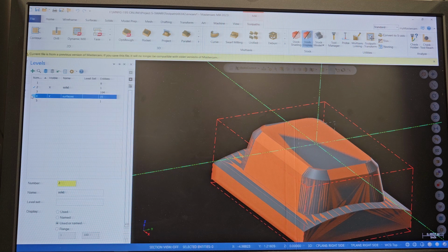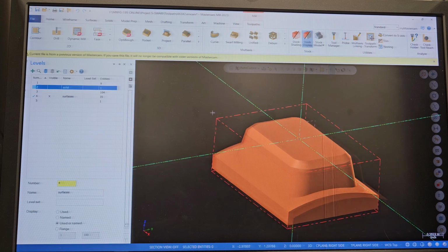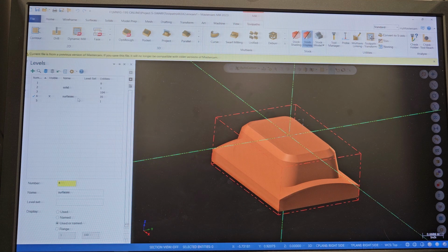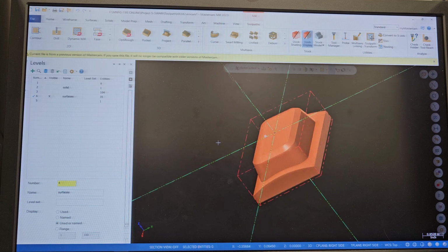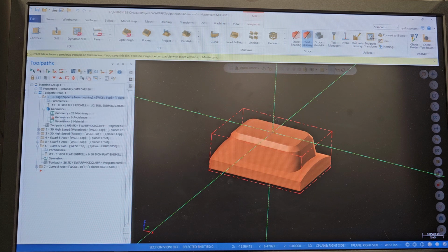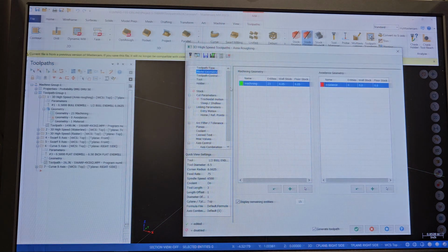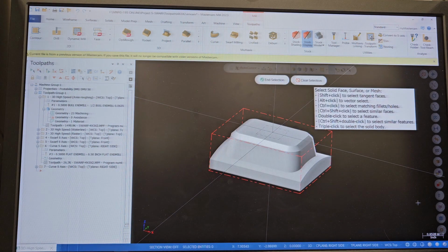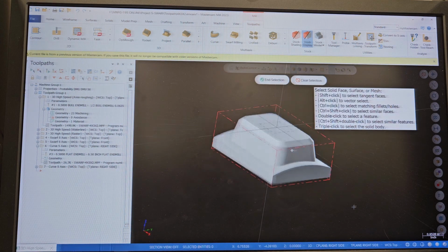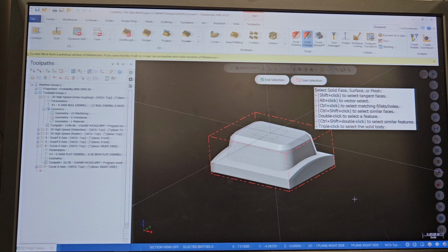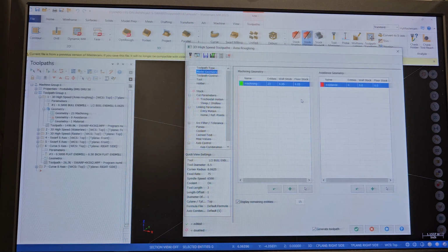Or you can, we have surfaces also. If you look here guys, we have surfaces also, and there are your solids right here. So you can use those surfaces also to machine this. So here, if I go on the geometry right here, all my surfaces have been selected. You'll be using, and leave .050 on the walls and on the floor for those surfaces.